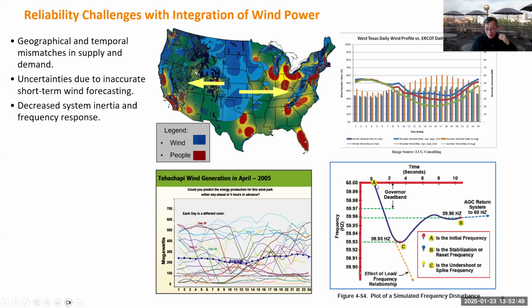So when you have a coal-fired power plant, because it has a very large rotor which has inertia, it means if you have a disturbance near that power plant, the rotor will take some time to speed up or to decrease the speed. For example, if you suddenly lose a load, the frequency will go up. If you suddenly trip another generator, the frequency will go down. The frequency change will not be fast if you have inertia.